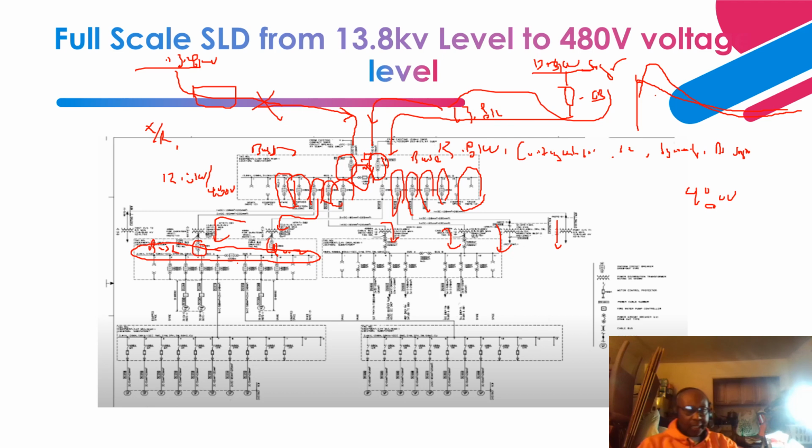There are protective schemes in place to detect the loss of voltage from one bus, with a relay, device 25, and some timers, that determine the level of the voltage and the delay for it to operate an automatic transfer scheme to close the tiebreaker.